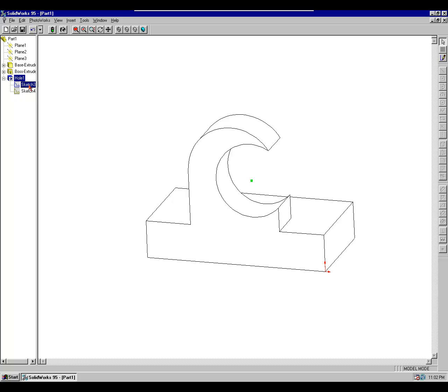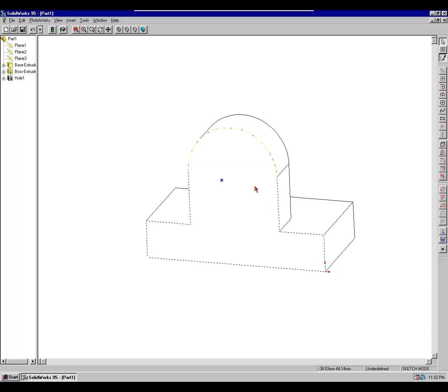Now, I goofed up, I forgot to relate it, so I'm just going to go back and edit my sketch and add that relationship between those. And you can see right there, I'm going to hold my shift key, select those 2 points. Oops, I selected my control key. So now I'll come back in. Oh, can't wake up the center point, but that was another functionality we added in later.